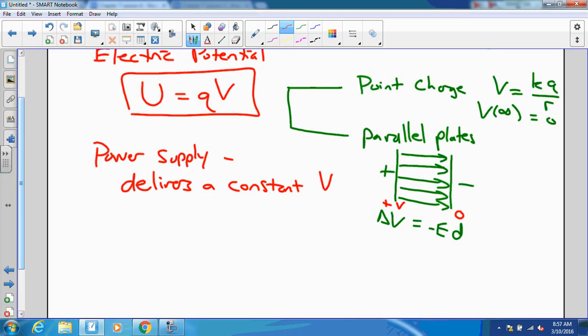And it's at 0 volts relative to ground. Here, this nominally should be 0. But because my ink is not perfectly conductive, it's going to be a little bit more than that. The major part of the resistance actually happens right where this thumbtack goes into the ink, right at that interface. You're going to have a little bit of a voltage rise right there.